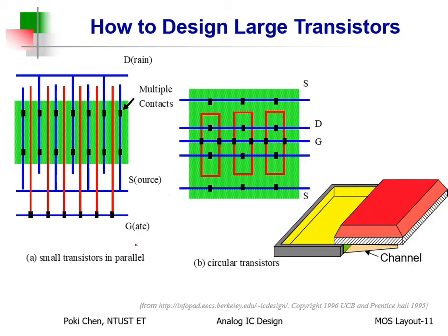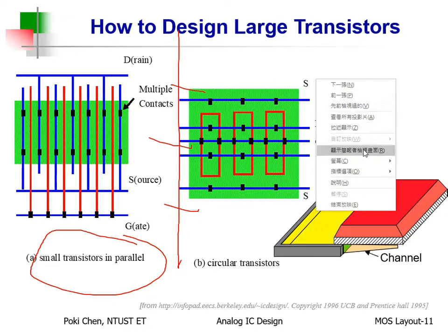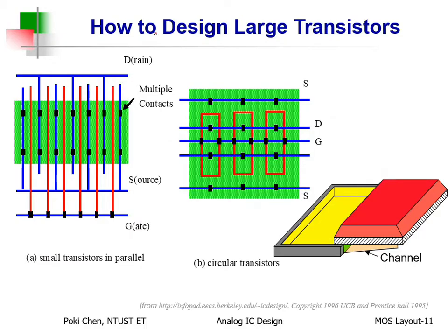From the very beginning, you can see that is the stacked layout. For a single transistor, you can cut a very wide transistor into half, into 4 pieces, into multiple pieces, then stack the layout. For what? Actually, to reduce not only the area, but also the parasitics. This is what I would like to share the first here.